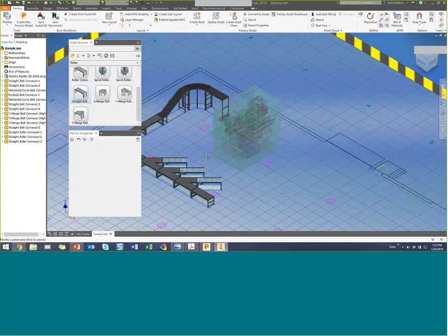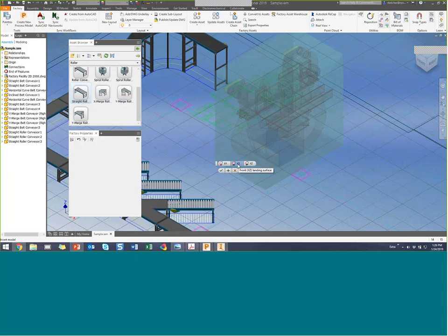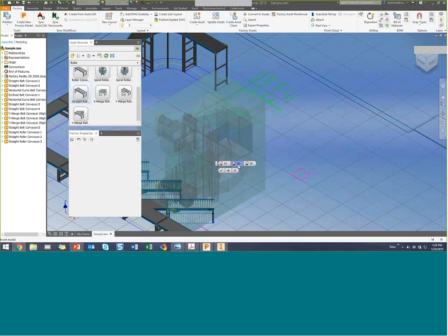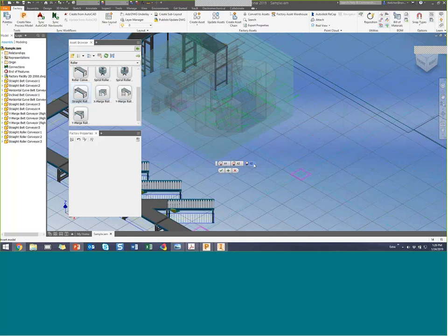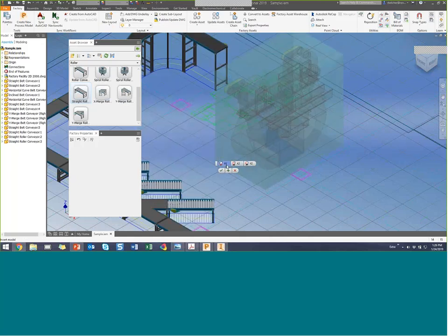And you'll notice that regardless of the operating system, the model lands on the floor. The factory utilities encases it in a bounding box, and the bounding box is what lands on the floor, no matter what. If you're working with a CAD tool that has a different up direction, Inventor is famous for Y being up, well, that's not a problem. You can orient the design with either X up, Y up, or Z up.